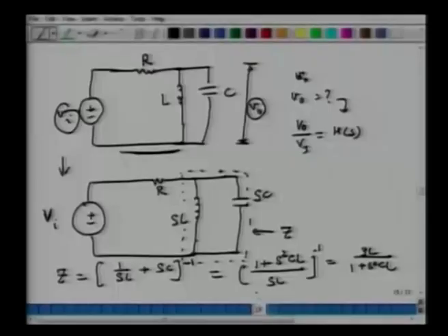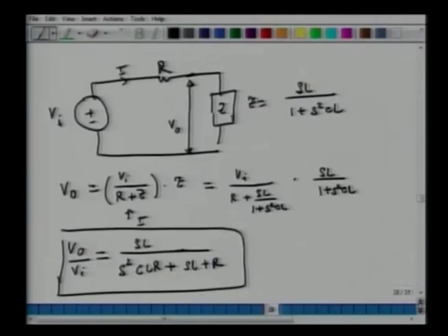So again, you are using complex variables and also the idea of complex time signals, and what you are doing is converting circuits which are in the time domain into the frequency domain by making these transformations. You are replacing L by SL and C by 1 over SC, adding them up appropriately, calculating complex current and complex voltage, and then mapping it back by taking their real components.